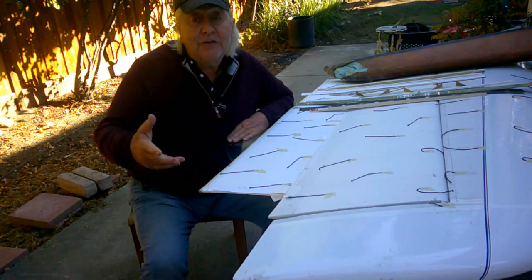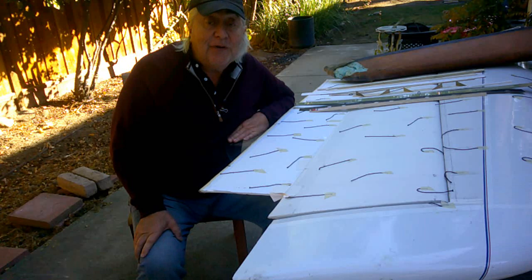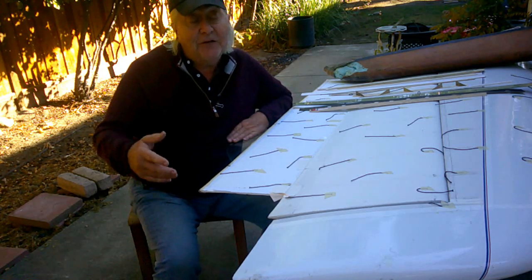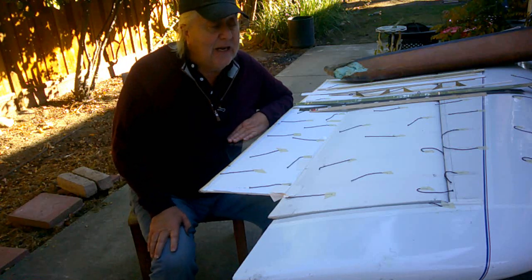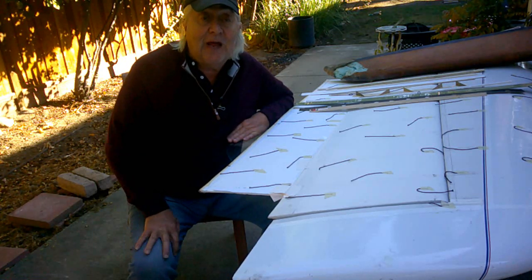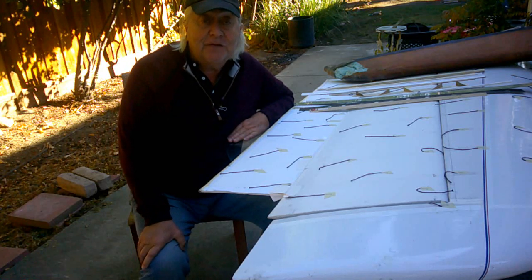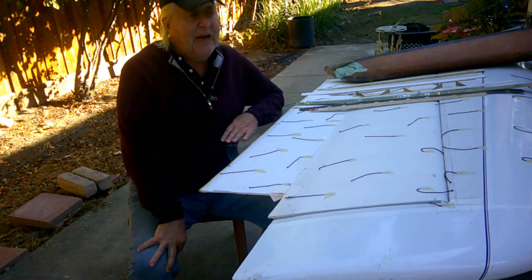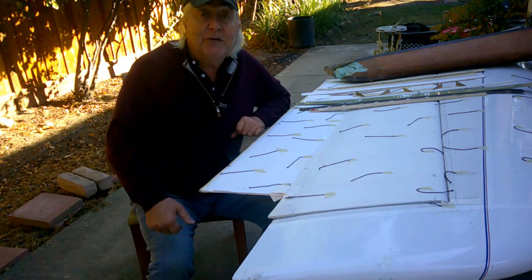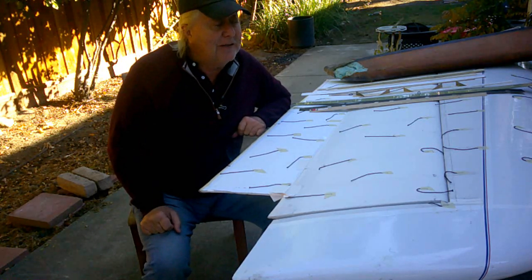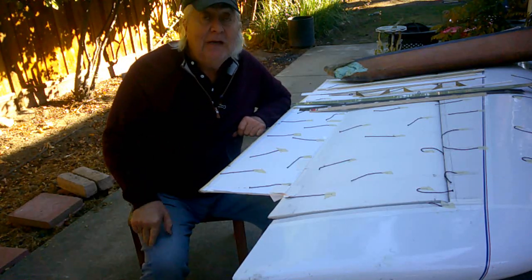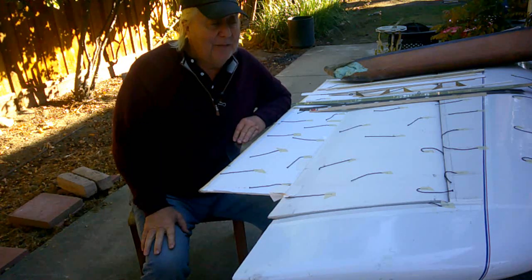And then I'll do what the Swift did. I'll add a little flap and have that flap deployed for takeoff. The Atos uses one. I think the Ecstasy has one. We're getting in the areas of wing loadings where you need a little bit of flap to generate some more lift so that you can foot launch. And that would get my stall speed down to, as it turned out, about 22 or 23 miles an hour. And with a little bit of headwind, I'll be able to get the thing off the ground. And we've seen that I've actually been able to do that.